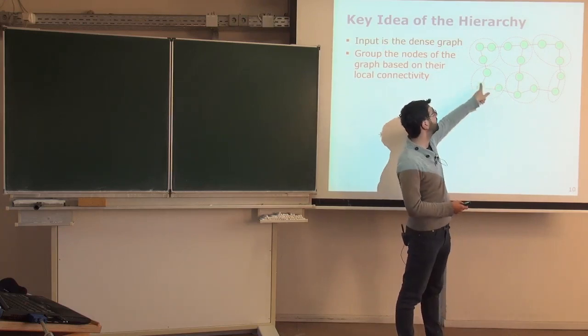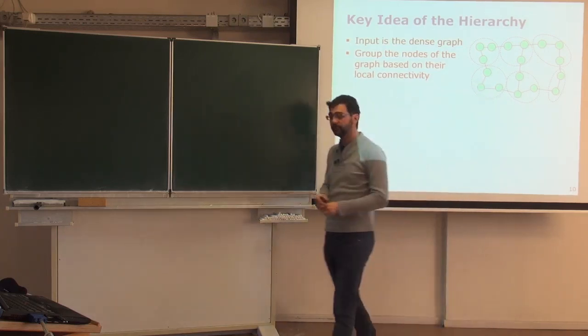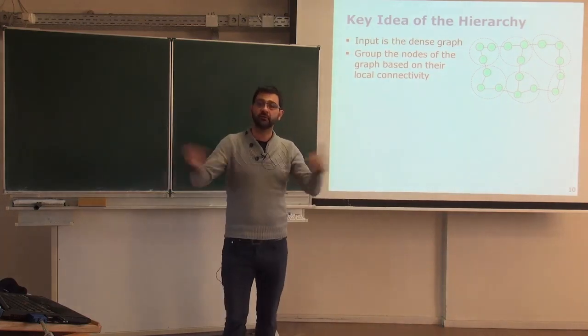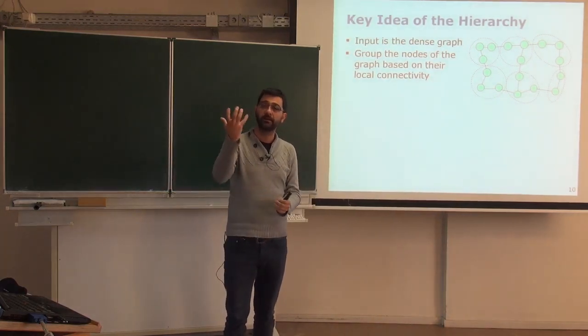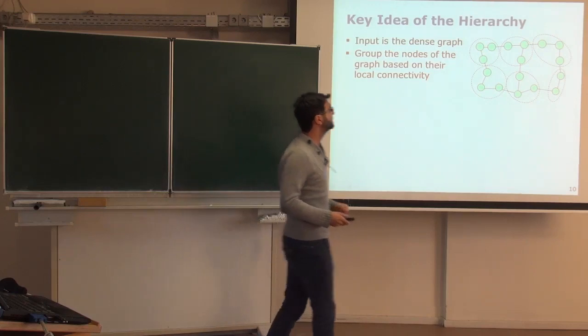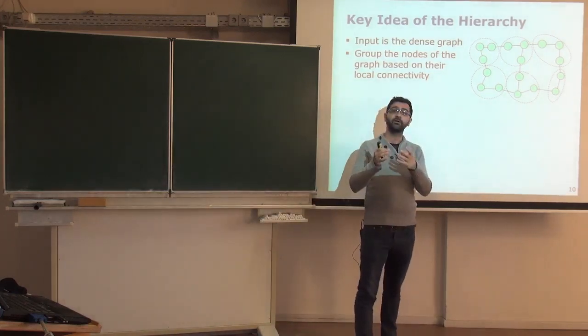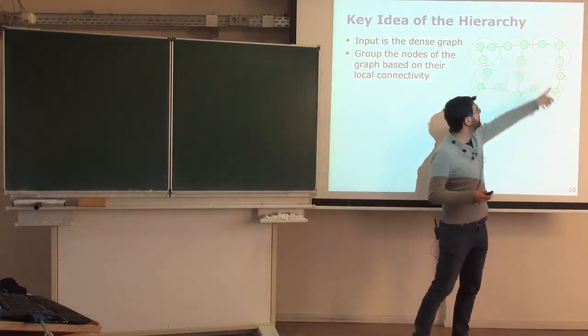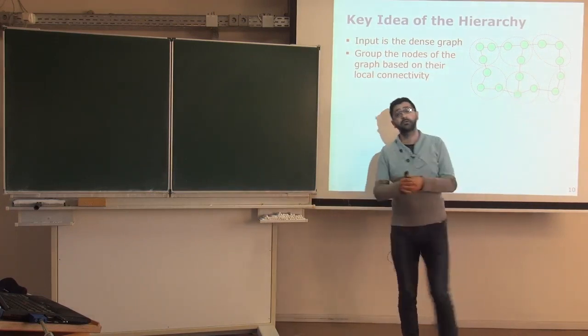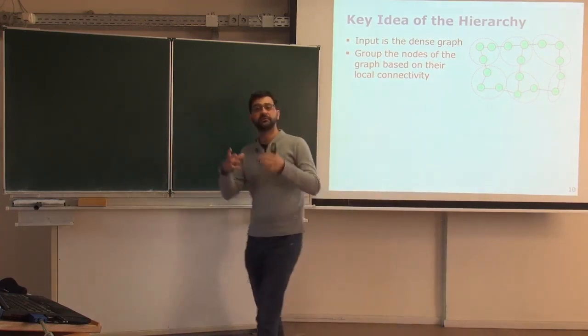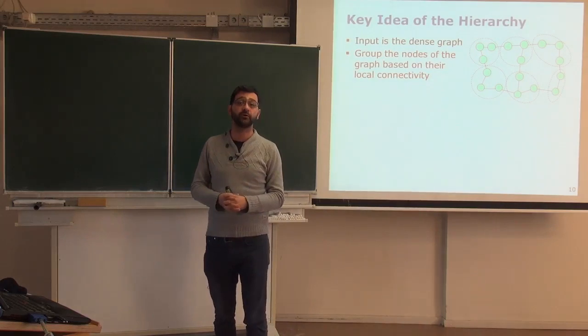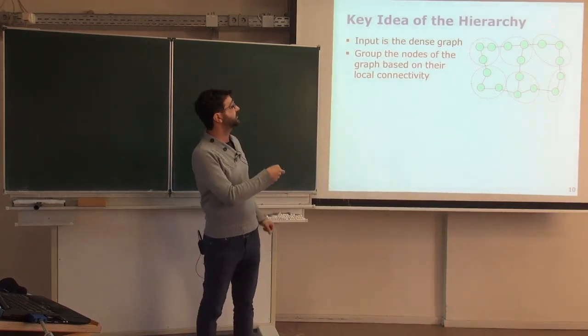The robot is moving around, and after a certain amount of space that it travels, you collect all the nodes into one cluster. Sometimes you need to exploit also a bit of data association. When the robot is coming back and you find data association, you reevaluate this clustering and put other nodes together.